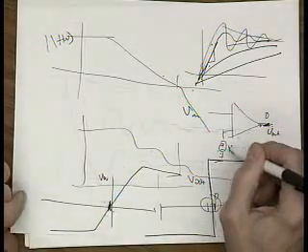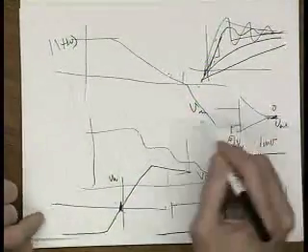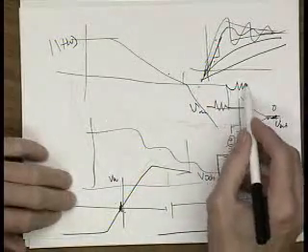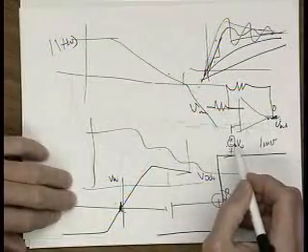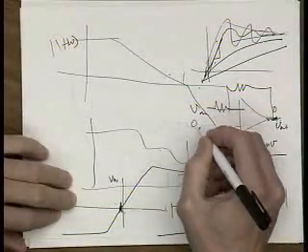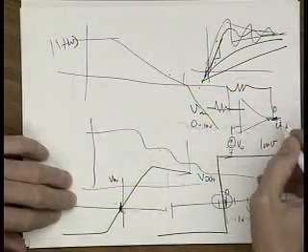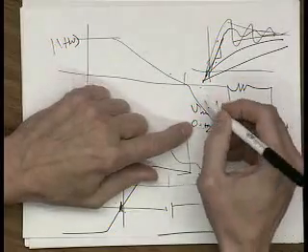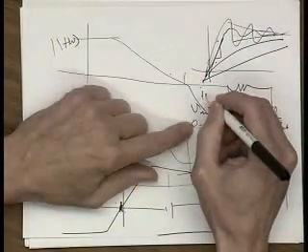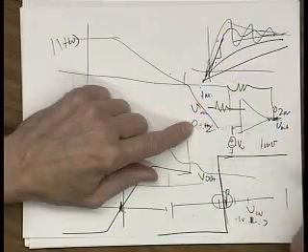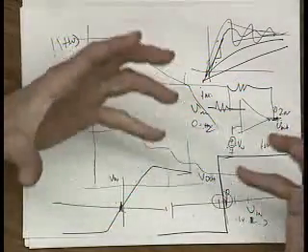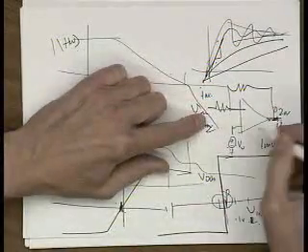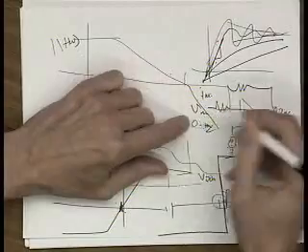The way this actually works in real life, of course, is that once you put this circuit into feedback, then you don't have to precisely develop this voltage. This means this input voltage can be offset by a millivolt or so. Well, it's only a gain of 2 after that point in time, right? And if it's only a gain of 2, a millivolt change on the input only makes a 2 millivolt change on the output. So you don't have such a strong dependency after you put it into feedback. It's only when you're open loop and you have this huge amount of gain that you have to worry about getting this input voltage exactly right.